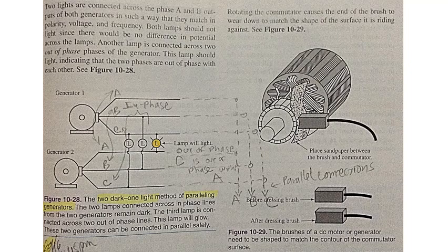Electrical overload. Another cause of failure is electrical overload. Electrical overload causes the electrical insulation to break down, resulting in a short circuit or ground condition. Most times the damage can be detected by the naked eye. A dark discoloration is a sign of excessive overload of a conductor.